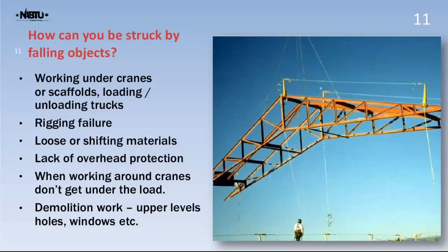So the best solution, you can see that this fellow has what's called, let me get my pointer here and point this out to you right here. You can see that's a guideline that they're using, or what's called a tagline, so he doesn't have to be underneath that structure. So remember, loose and shifting materials can fall off. Lack of overhead protection can create a hazard. There's just nothing above you to keep stuff from hitting you.